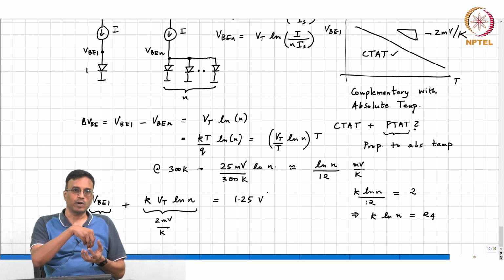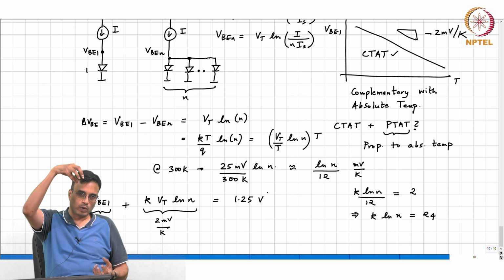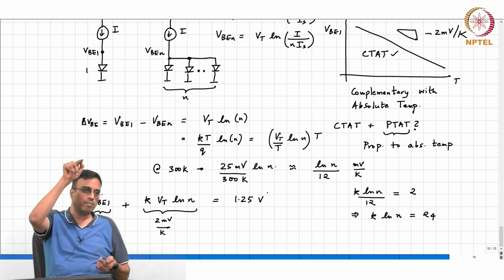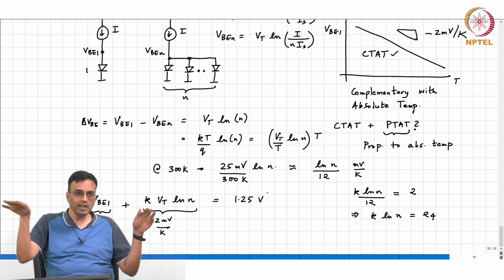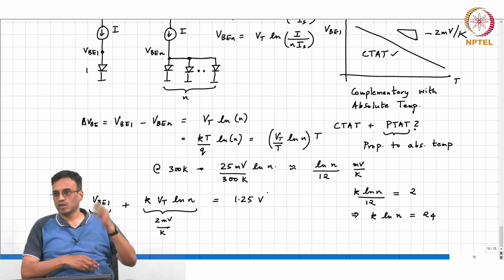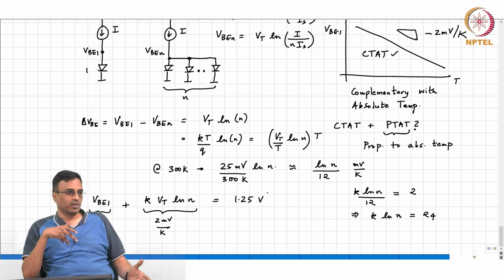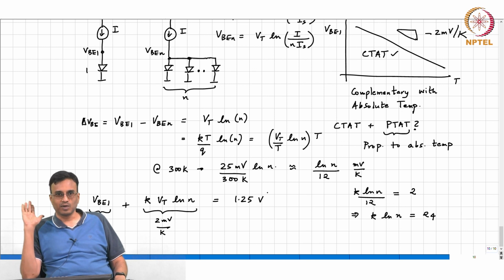The hollow tube will expand downwards. Inside there is mercury. In the hot weather, the mercury column expands in the opposite direction, and with the right amount of mercury, you can make sure that the center of gravity of the pendulum remains constant. So, as you can see, the principle isn't rocket science.